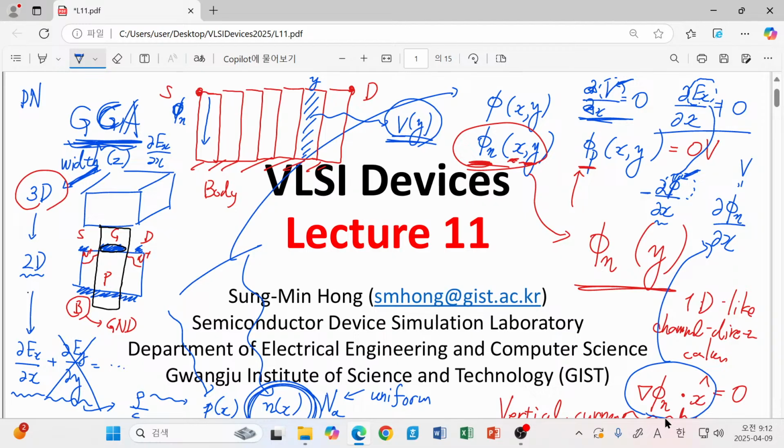So you have electric field, and at the same time change of your electric field, but that does not necessarily mean that you have a current conduction. The condition for having zero electron current and hole current is that quasi-Fermi potential, for electrons and holes, should be a constant. It means that gradient vanishing. Then you will have zero current.